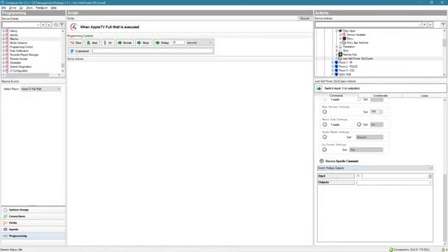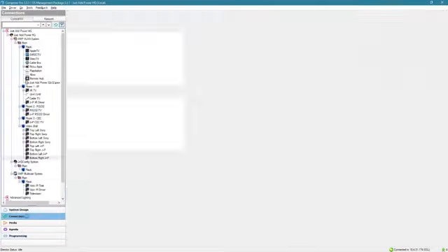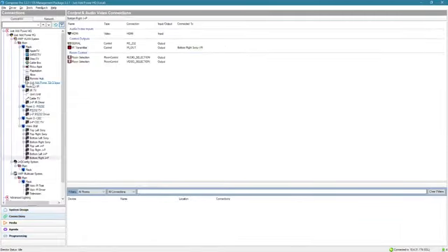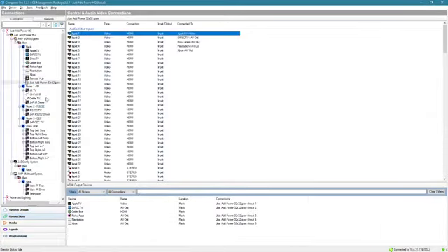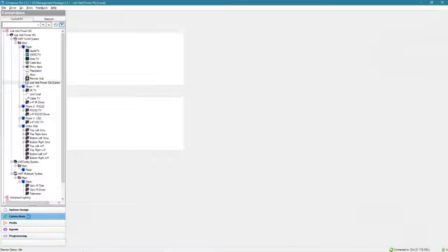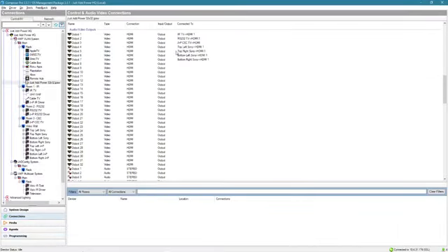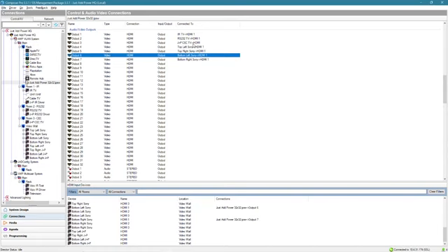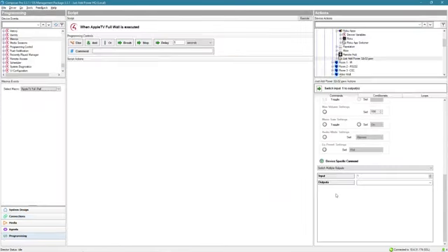Device specific command, and I'm going to do switch multiple outputs. So my Apple TV, based on my connections, is input number 1. So I'm saying input 1, and my outputs, does anybody remember? My outputs for the wall are outputs 4, 5, 6, and 7. So input 1 to outputs 4 through 7. Drag that over, and that is my switching macro to set all 4 TVs to the Apple TV.